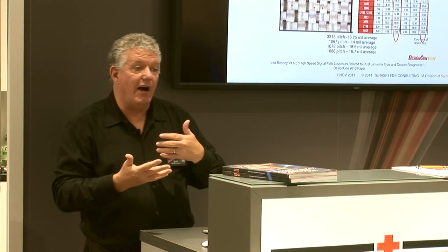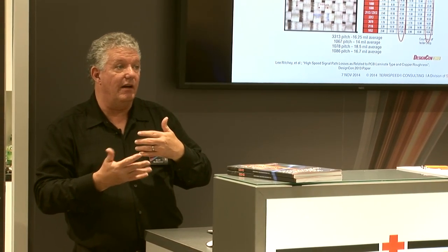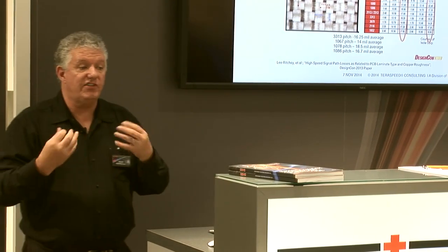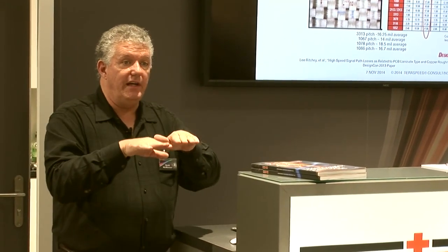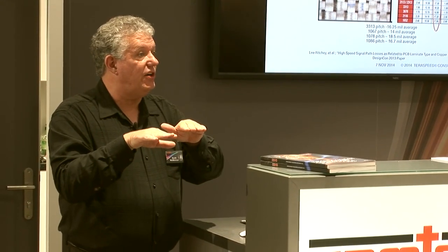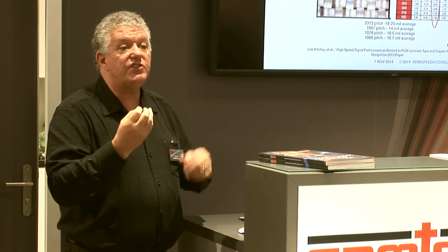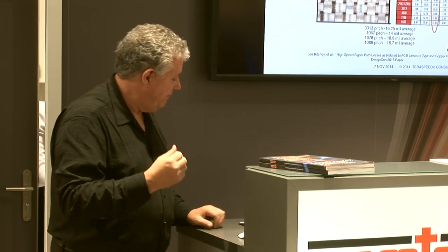So that's another option that we have for eliminating skew. None of this totally eliminates skew except the matched dielectric property materials. But it gives us a number of options to essentially increase the bandwidth of our system and increase the reliability of our system.